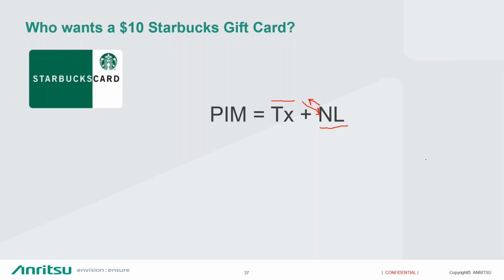Okay, and then the last one I have in here is, does a calibration PIM diode come with the IQ fiber master? Yes. At the end of the day, if you're familiar with RF, the PIM diode is a very strong PIM source, but you can use other strong PIM sources like a ball of steel wool. But yes, the PIM diode does come with the IQ fiber master.